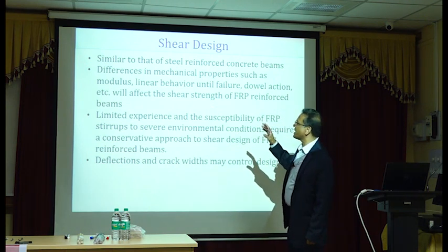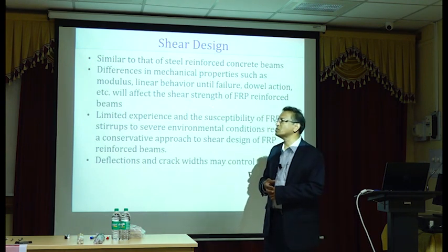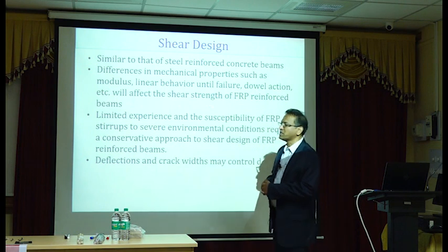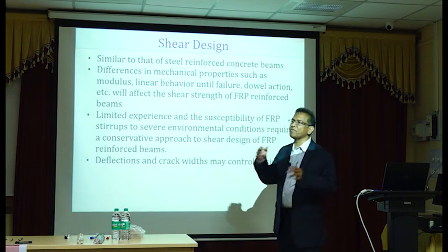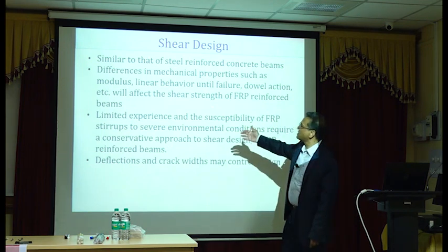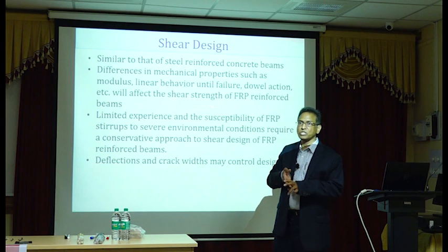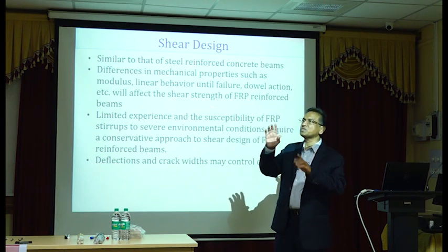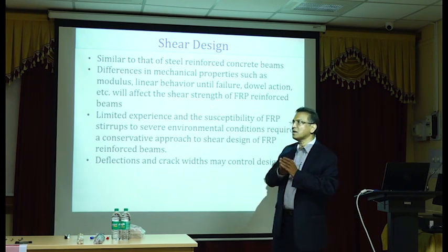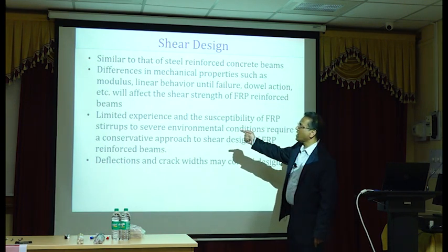Also, there is very little experience with failures. Failure is a very bad thing, of course, but failures also give us a lot of lessons. We learn from failures. Of course, that's the reason we test in the labs, so we fail everything in the lab instead of in service. So very little experience. Stirrups have the tendency to be affected by moisture. So you think it's an FRP bar, so I can place it very close to the surface. But they also absorb a lot of moisture, so that's a problem. So if it is a severe environment, stirrups will have a problem.